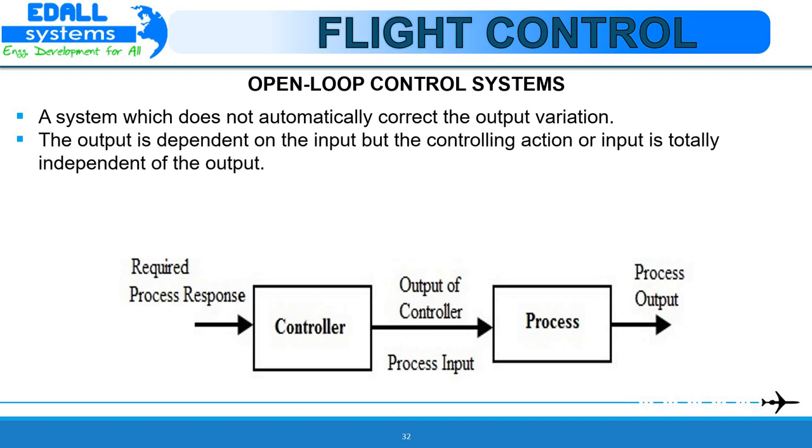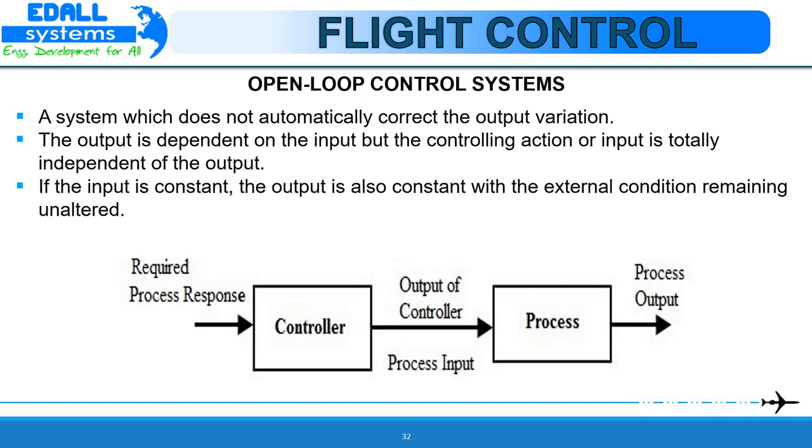The advantages of the open loop system are that it is very simple to construct, and very convenient when output is difficult to measure. Such systems are easy from a maintenance point of view. Generally, these are not troubled with the problem of stability. Such systems are simple to design and hence economical.